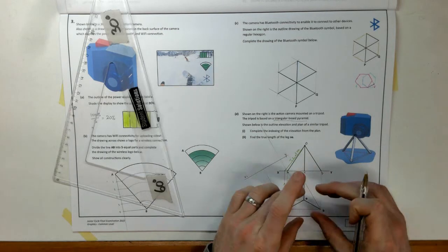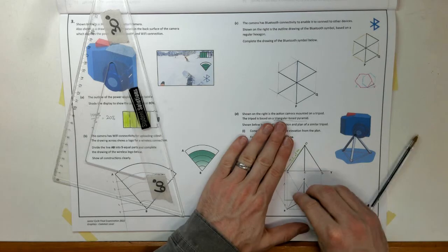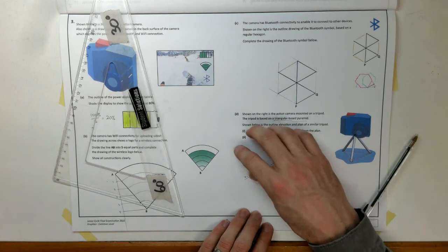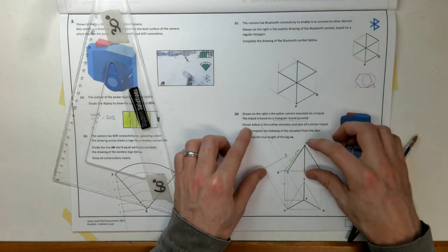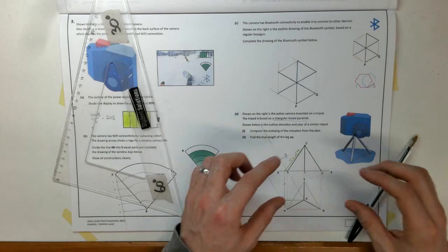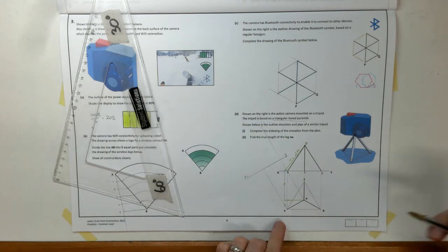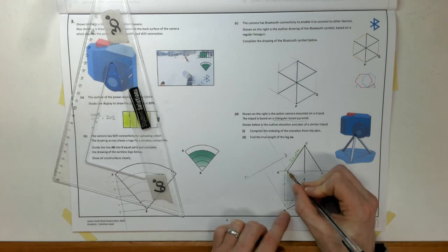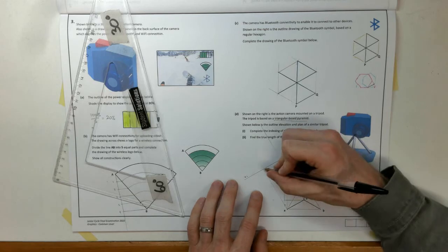Now, because I'm projecting from plan, right, same way as if I projected from plan here, I create an elevation. I'm projecting from plan again, so I'm creating an auxiliary elevation. Okay, and elevations share heights. Okay, same way an elevation and end elevation have the same height. So let's go through it. Point A, the height of point A is 0, it has no height, it's on the XY line, so that is point A.